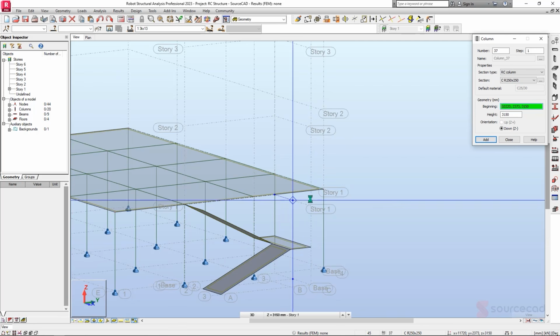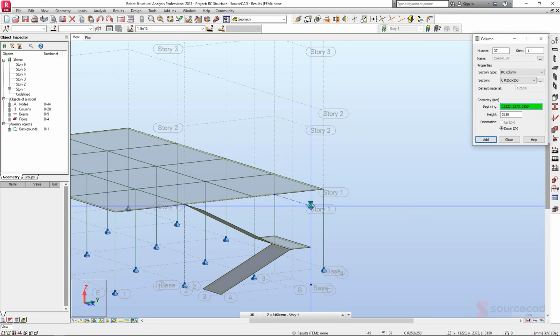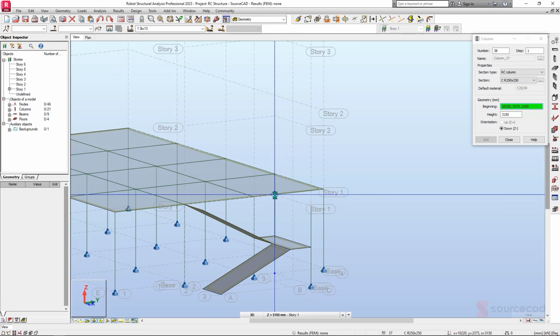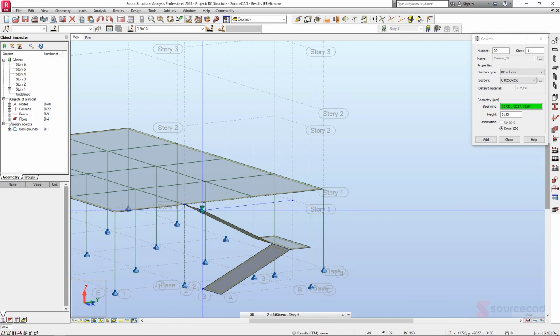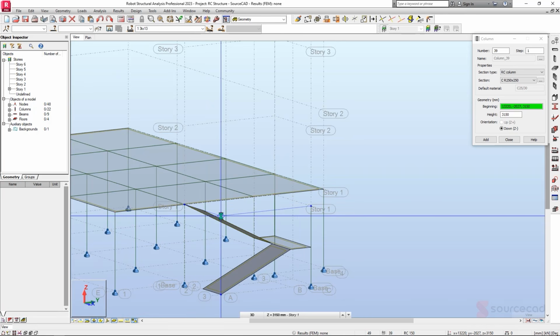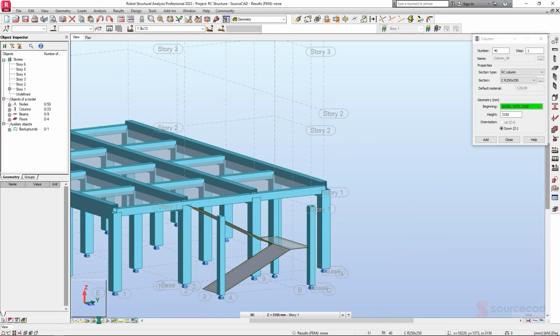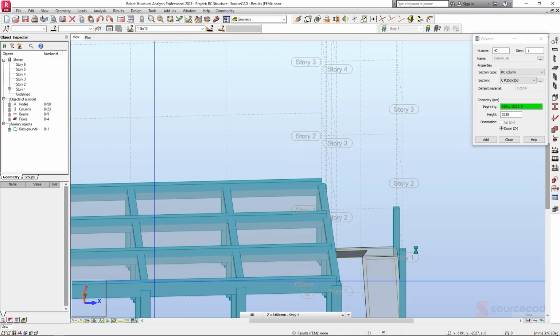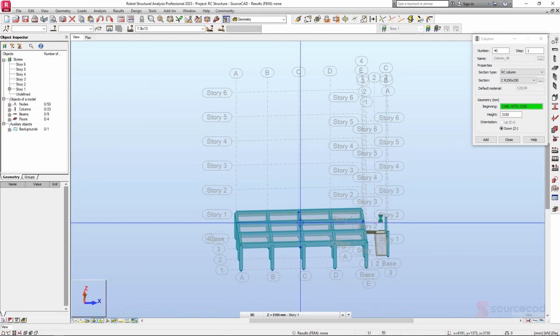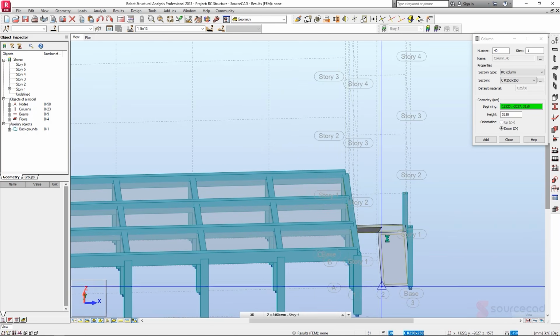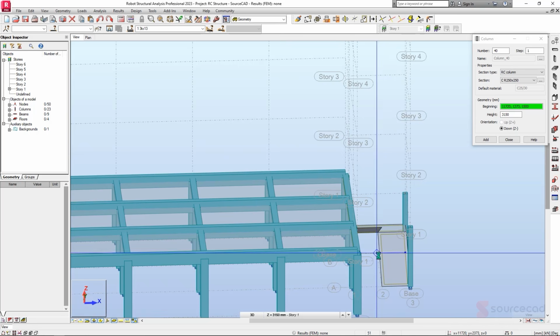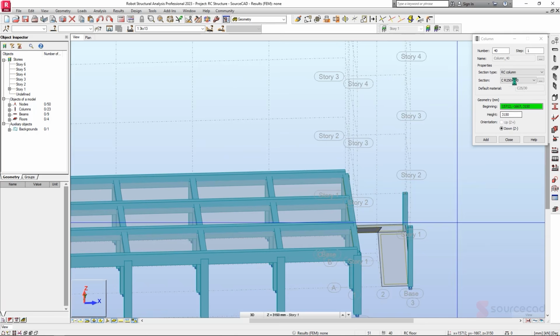So we can specify where we have story 1. You can clearly see that we have a connection from that point. So over here, down, done. Over here, down, done. At this section, we can add it here so that we add a beam on this other section. So if I was to turn on my section shapes, you can clearly see how it looks like, something of the sort. So we can add a landing beam on this other side instead of having a column in between here. But where we might need a column is actually here, but as long as we have a strong beam.